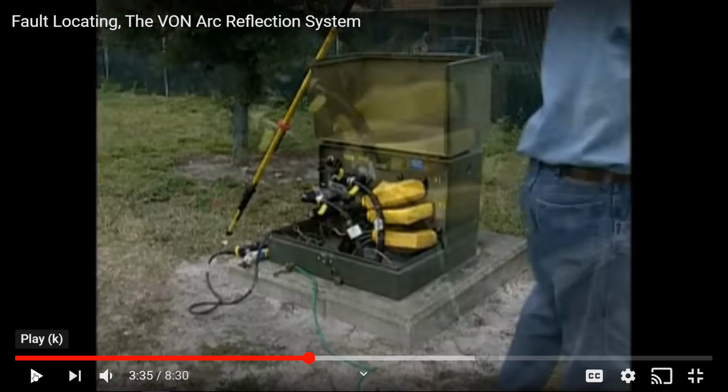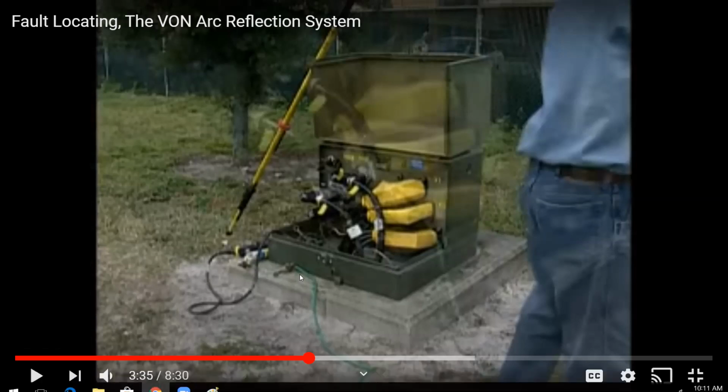If for some reason you have a fault on the conductor, or something goes wrong on the conductor, that coil on the ground will intensify and make the voltage go even higher. So you have to uncoil the ground lead, which is coiled up on the machine here. He uncoils it and stretches it down the ground in a straight line before connecting it.